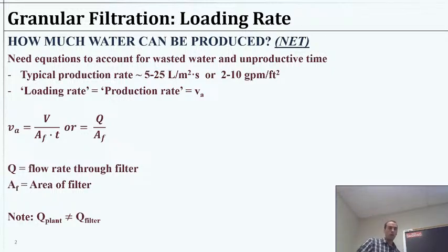So on the whole, we could say that we have some flow rate demanded by the entire plant. That would be our Q in this case. So this would be our Q for total demand. And we could take a look at how much we need in terms of what we will call a flux. I heard some of you mentioning that from another class you're dealing with flux, right? So flux, in the sense of water across our filter here, is really just a flow rate divided by the area across which we're flowing. So that's going to be our definition of flux.